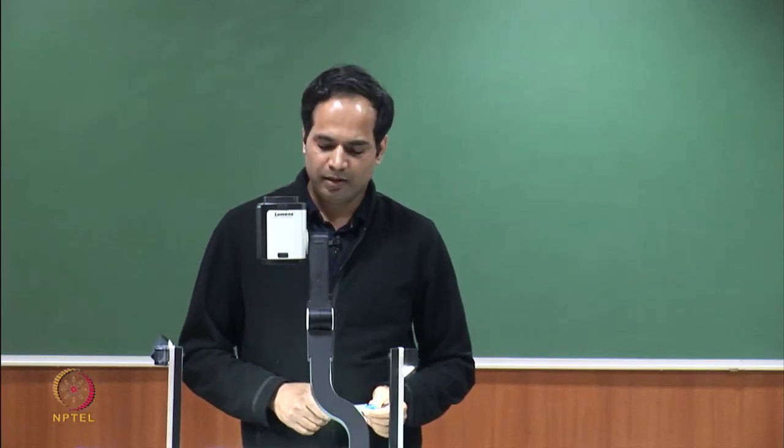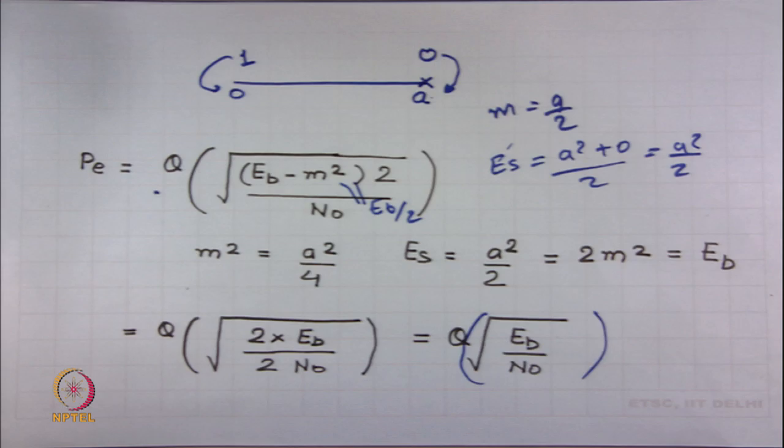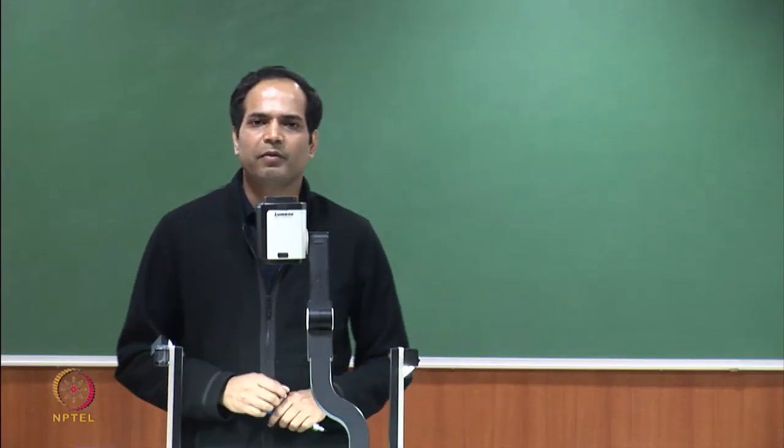All right. So, we have understood quite well how the detector works in case of binary antipodal signals, and so far what we have been assuming is when you have to transmit a hypothesis, you are transmitting one numerical value, plus A or minus A. Let us have more fun by generalizing this, and let us now say that when you have to transmit a hypothesis, instead of transmitting one numerical value, you transmit a vector. And why is this important? Because actually when we have to transmit a hypothesis, we will be transmitting a waveform, and waveform is nothing but a vector.